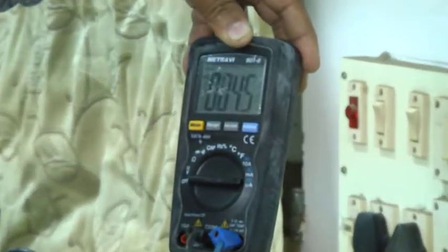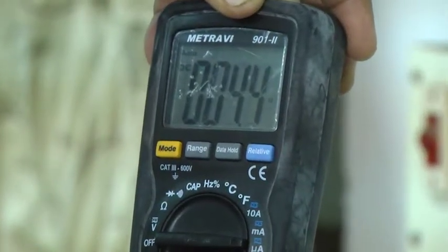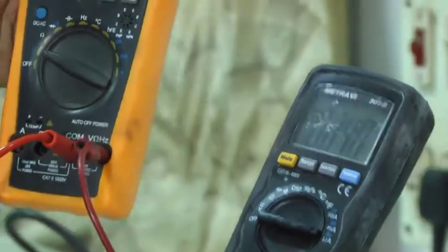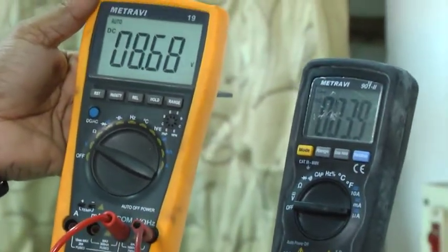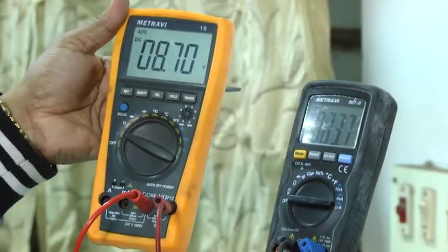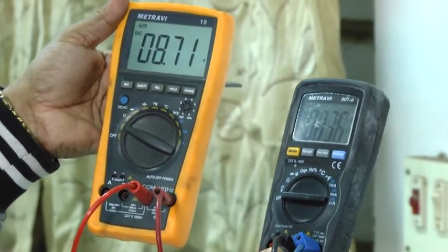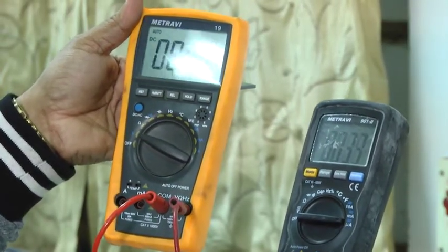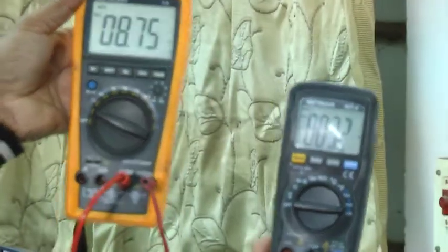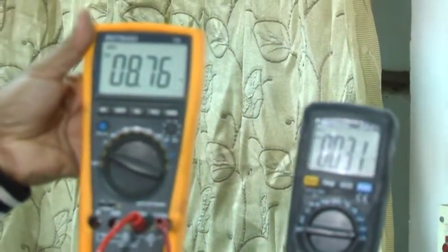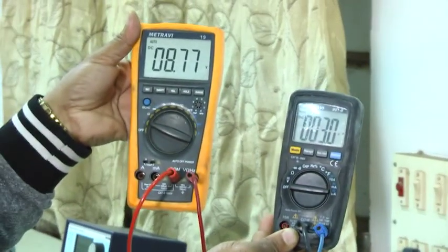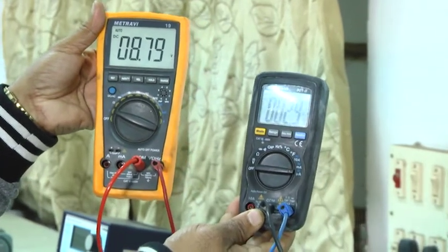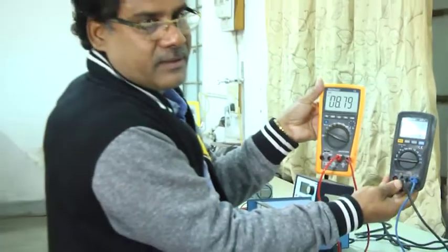So yes, 4.5 microampere, 4.4. This way it is going towards 0, and the voltage is going towards 10. So we have to note down both readings, for current and voltage. Then we will plot that data and you will get the curve, and then we will use a log plot to find the slope, and the inverse of the slope will be your RC.